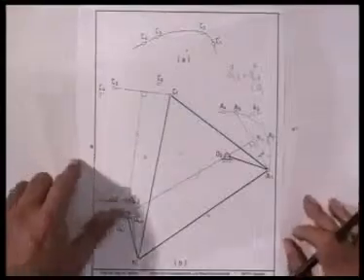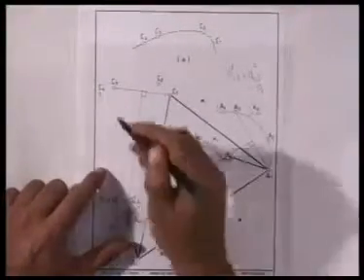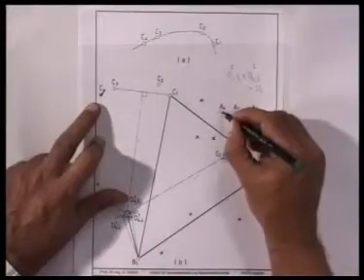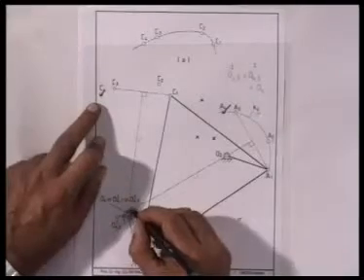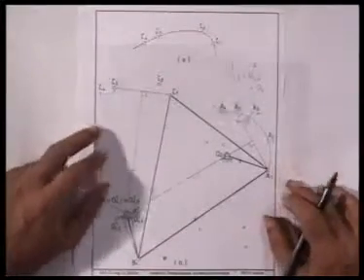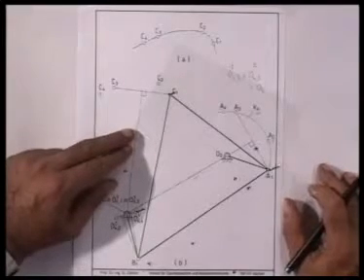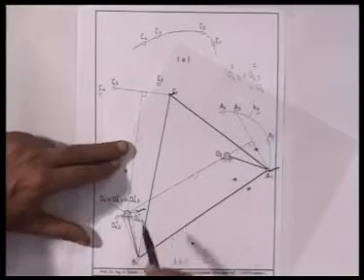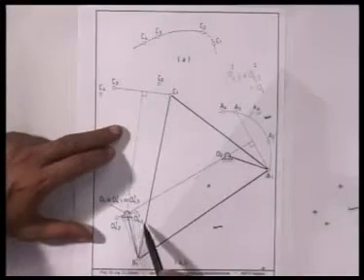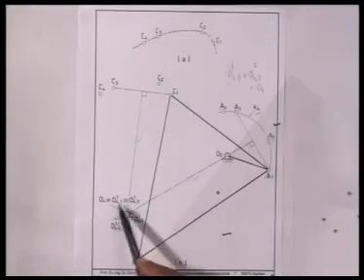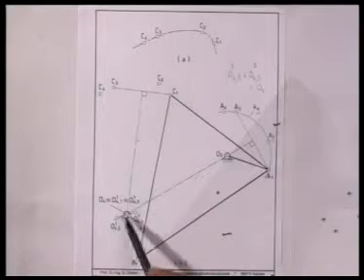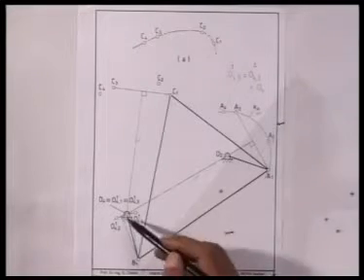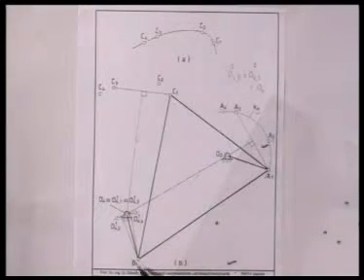Similarly, for the fourth configuration, I mark C4 and A4 and O4. Then make C4 coincide with C1, A4 coincide with A1, and wherever O4 goes, the O4 has moved here, and that I call O4, 4, 1. So 2 of the 4 inverted positions coincide. So 4 inverted positions give me only 3 distinct points, and I can always draw a circle through these 3 points, and the center of the circle is determined here at B1.